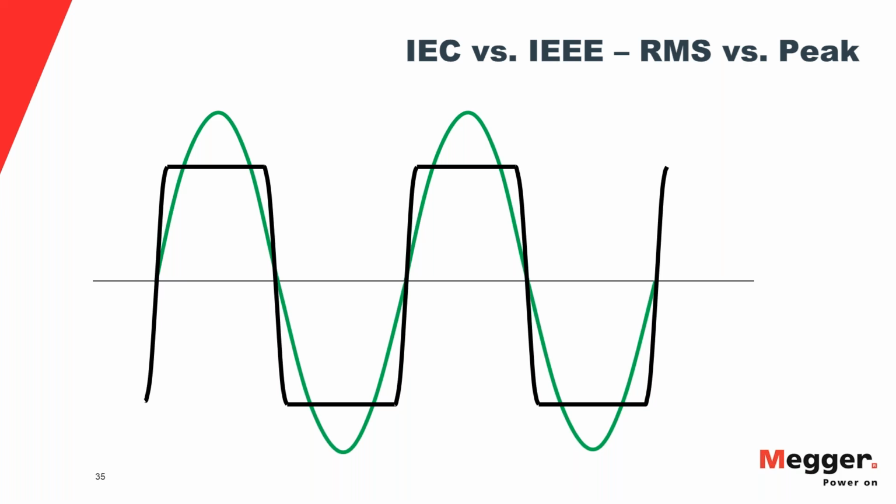So if you come to a 20 kV cable where the operating voltage is 12 kV, and you do an IEC test, which is 3 times operating voltage, which puts you at 36 kV RMS, the peak of the sinusoidal test set will be 41% higher than that. So you have to multiply 36 times 1.4 roughly, and that is your peak stress in the insulation.